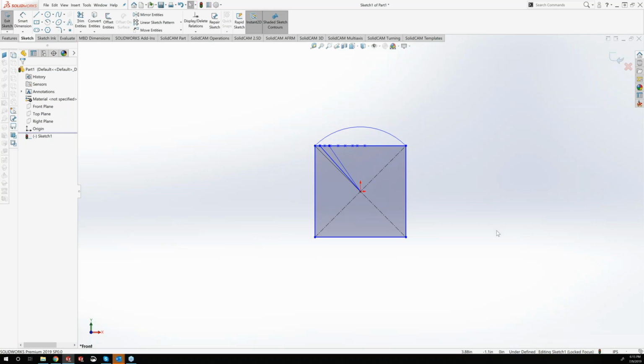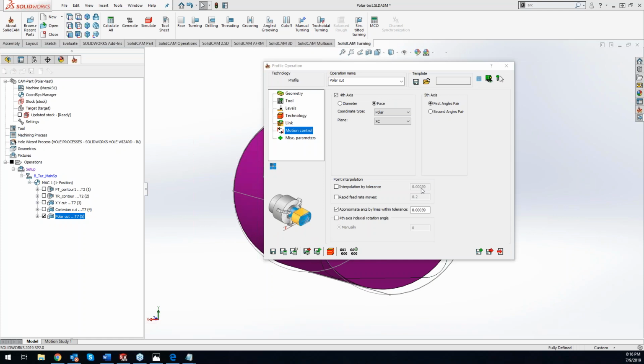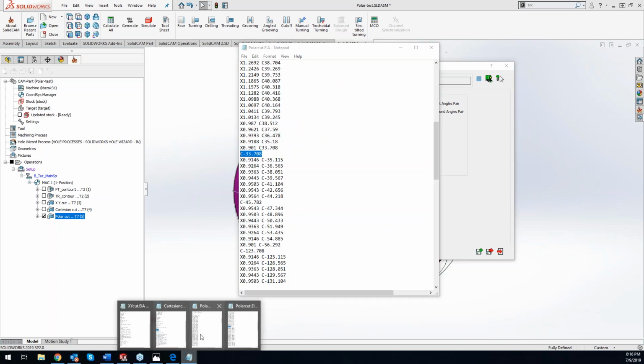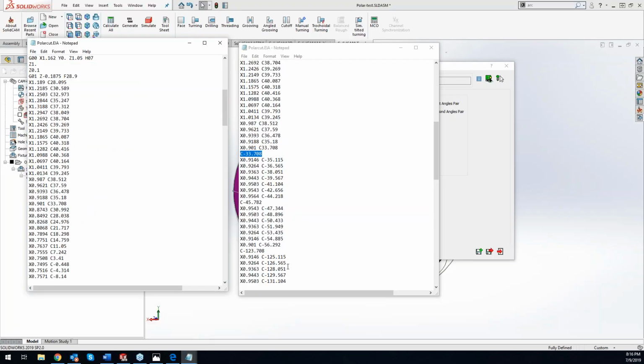So let's go back to your screen, Kevin. Yep. One second here. That way we can compare that to the G-code output again. Yeah, and what Greg was saying with those points is, by having this turned on, those points are created basically every 4/10. Now, depending on the resolution that you want, you can change those values. Just know that the smaller the number, the closer you're going to get to a true line, but the more code you're going to have as a result.